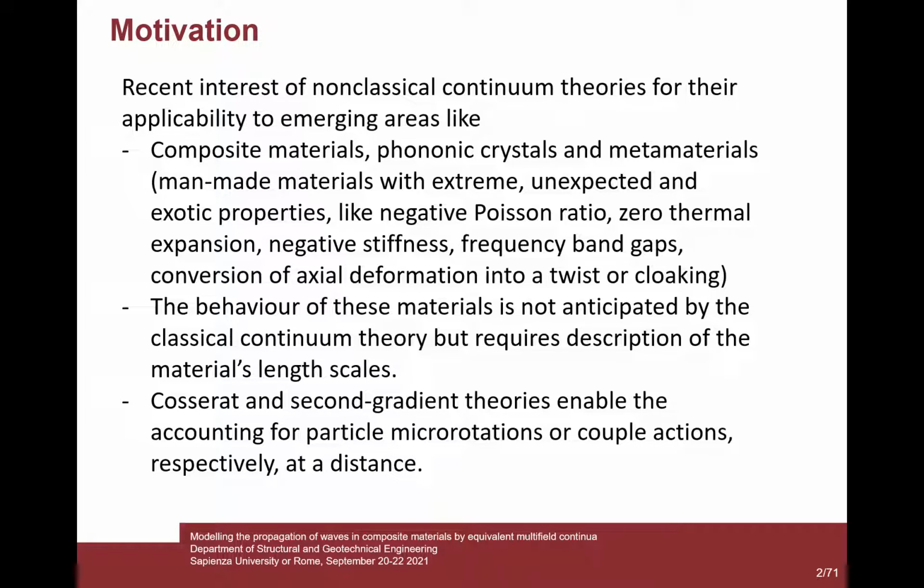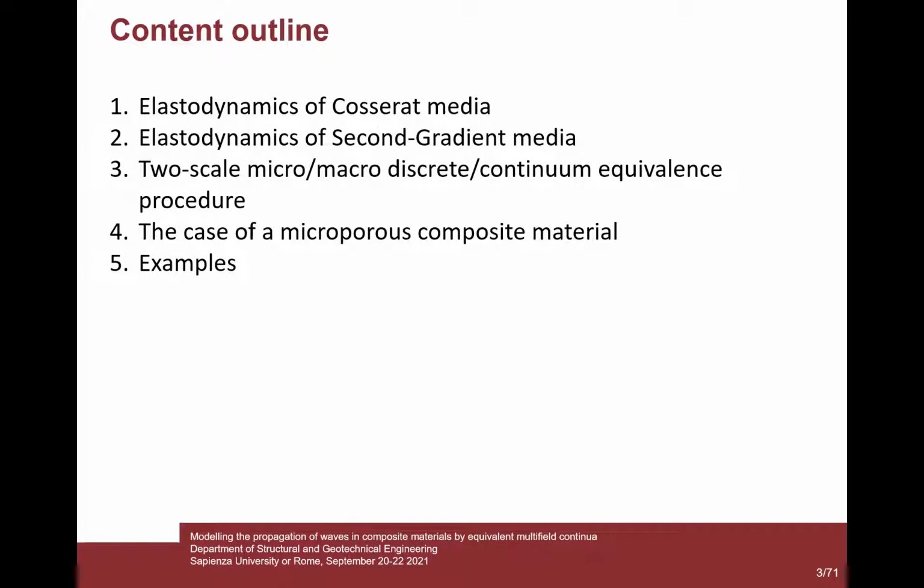How is it possible to model this kind of phenomena? This is possible by using Cosserat and second gradient theories. These theories enable the accounting for material particle micro-rotation, or the transmission of couple stress actions, or even actions at a distance. The content of this presentation will be first the presentation of the elastodynamics in Cosserat and second gradient media, and then the description of this two-scale micro-macro discrete-continuum equivalence procedure, which is used to model, to obtain a macro